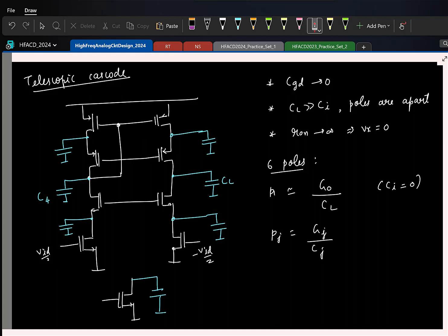For DC calculations you could do that because we don't consider capacitors. So for common mode excitations we saw this become symmetrical. That's only for DC. The moment you put a capacitor, that will no longer be the case. At DC it will be symmetrical, but at higher frequencies it need not be. That's the point.